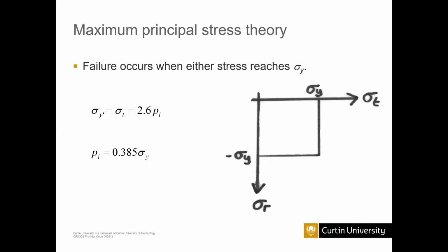If it is equal to the yield strength, in this case the ratio is given as 0.6. Then the sigma t value is this one. If that value equals sigma y, that means the strength, you can draw this in the fourth quadrant, because the sigma y value is a compressive load.